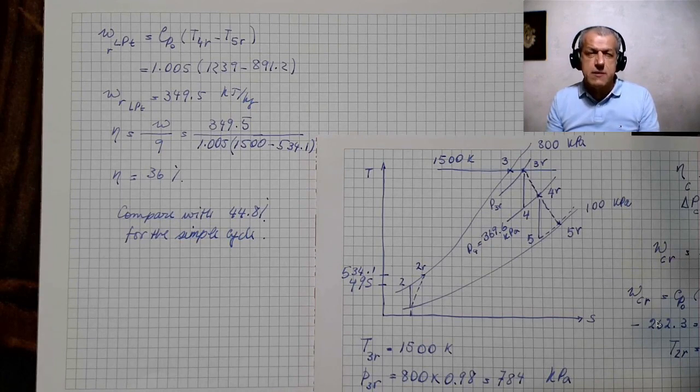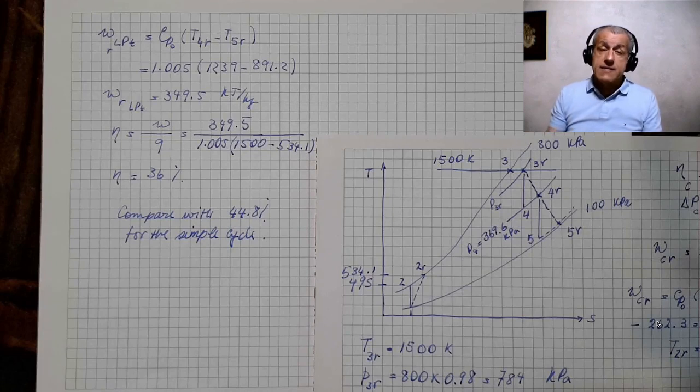In fact, this is the high end of what you could expect for Class E gas turbines. Usually, such turbines like the V94-2 produce something around 33% to 36%, and they are Class E gas turbines.